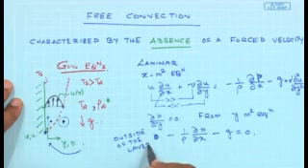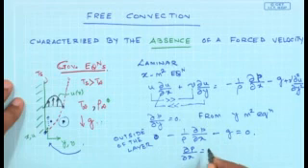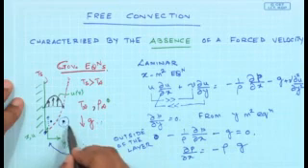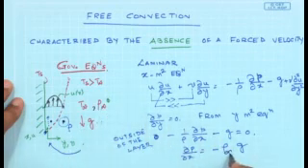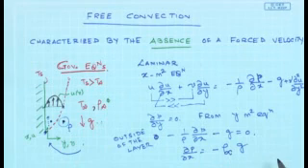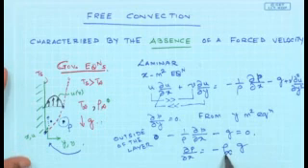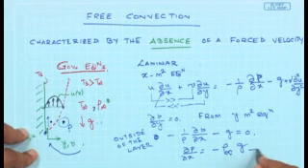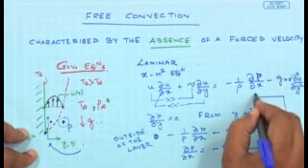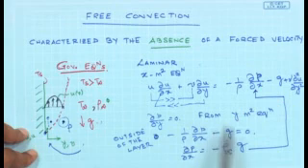So when you do that, we also understand that ∂p/∂x would be equal to -ρg, and the ρ refers to the ρ over here. So therefore the ρ is essentially ρ at infinity. So this is what we would get for the pressure gradient in the x direction: ∂p/∂x equal to -ρ∞ g. So it's straightforward. Now I am going to put this back in here.